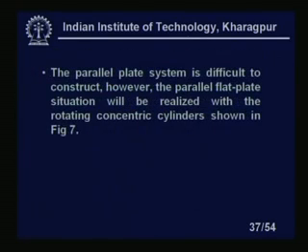The parallel plate system is difficult to construct, however, because this type of parallel plate is very difficult. Two plates are moving parallel, and I have some liquid in between the two parallel plates and the plates are moving, it is very difficult to realize. Instead, we can make two concentric cylinders, right, one cylinder stationary, the other cylinder moving, so that we can realize that parallel plate phenomena there also. That will be easier for us to make mechanically, to make the construction, right.